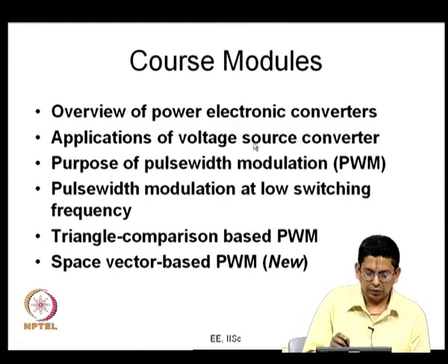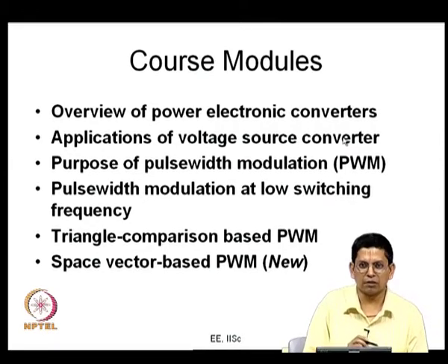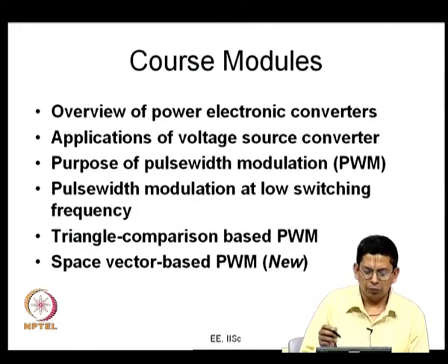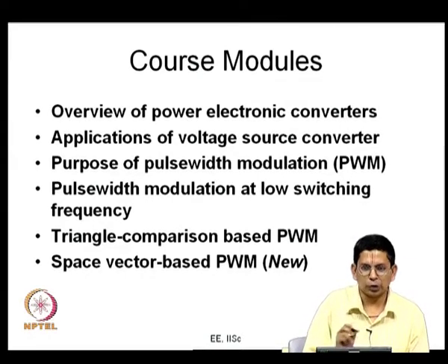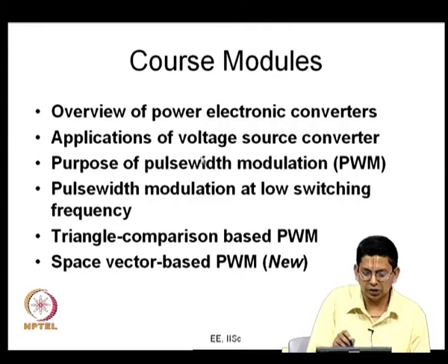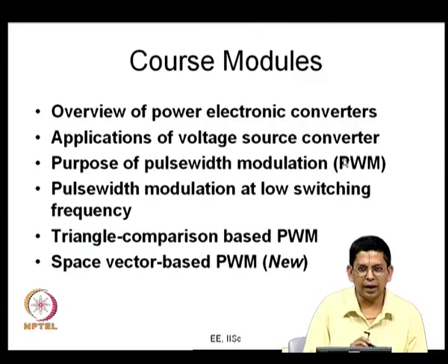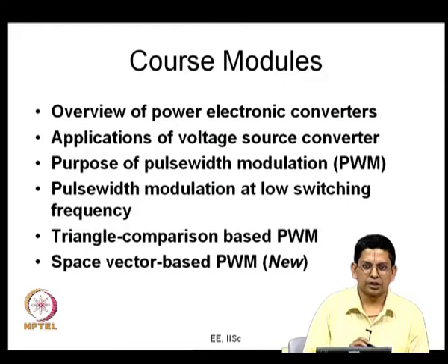We looked at various kinds of power electronic converters, started from switches and then we went on to DC converters, buck, boost, etc., and we looked at voltage source and current source converters, multi-level converters, etc. Then we had a particular focus on the 3-phase voltage source converter, and we looked at applications of voltage source converters. The most important application that we are concerned about here is motor drive, that is an induction motor drive.